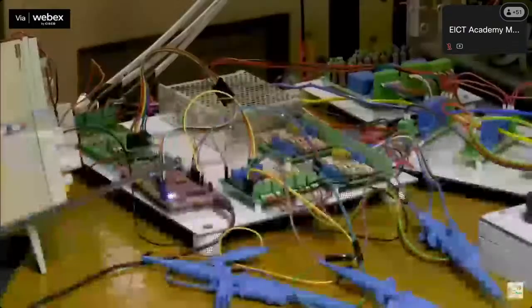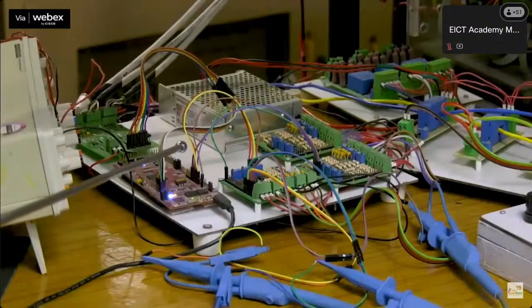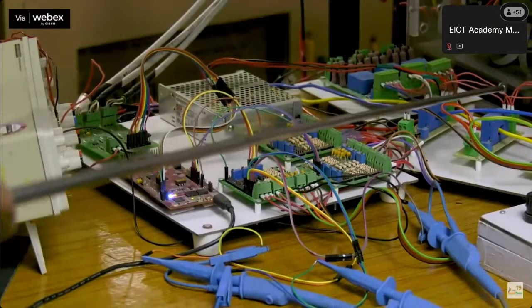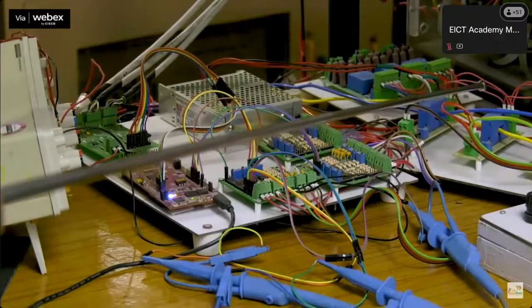Implementing a control system in DSP requires three-phase voltage and current signals along with the DC bus voltage. The three-phase voltages and currents are measured through sensors. The proportionate output of the sensors is a sinusoidal, bipolar signal. This bipolar signal cannot be given to the ADC pins of the DSP controller because the ADC converts only the positive side of the signal into digital form, and the negative side is always converted to zero. This causes a significant loss in signal.